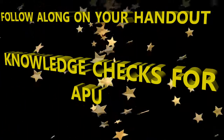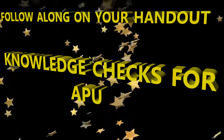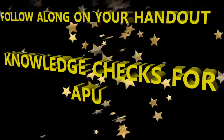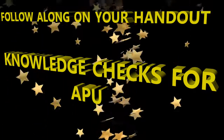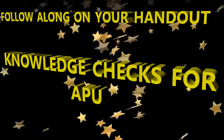All right, question number 23. Before accessing the APU doors, what must you do first in the cockpit? One of the things you want to do, if you're going to access the APU doors so that they open, is keep those circuit breakers open. So that needs to happen first. Open the aircraft circuit breakers.